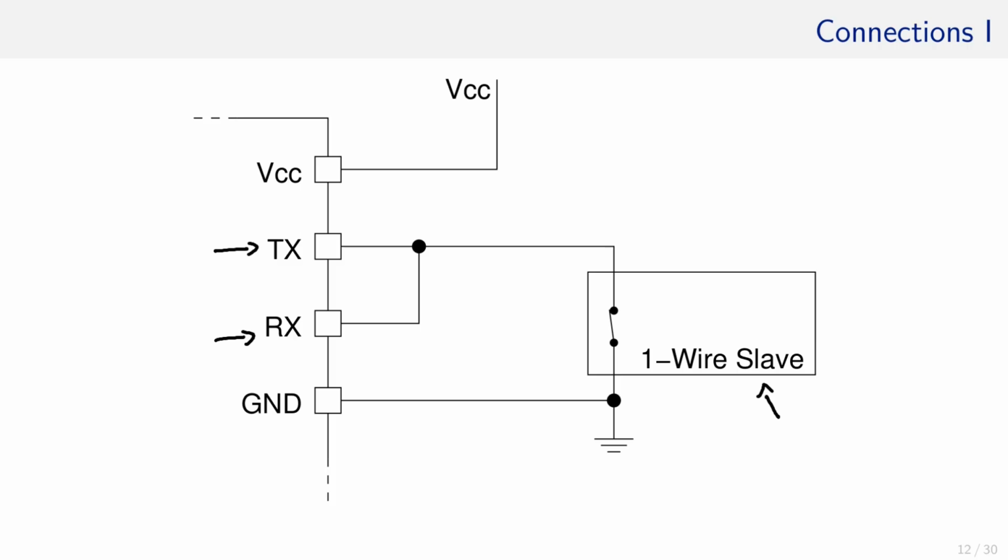In many situations, shown on the previous slides, TX transmits a 1, but the slave wants to write a 0 to the wire, hence this switch is closed. RX will read a 0 because no pin is strong enough to have voltage on the wire if it is connected to the ground.